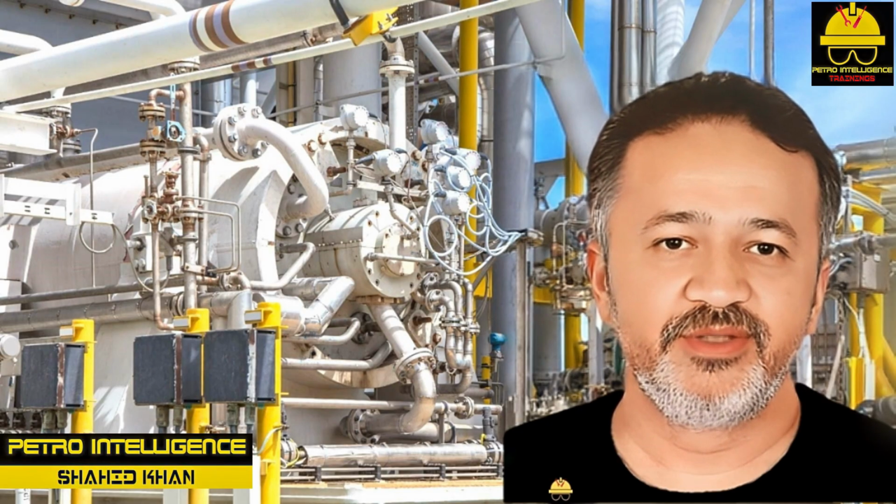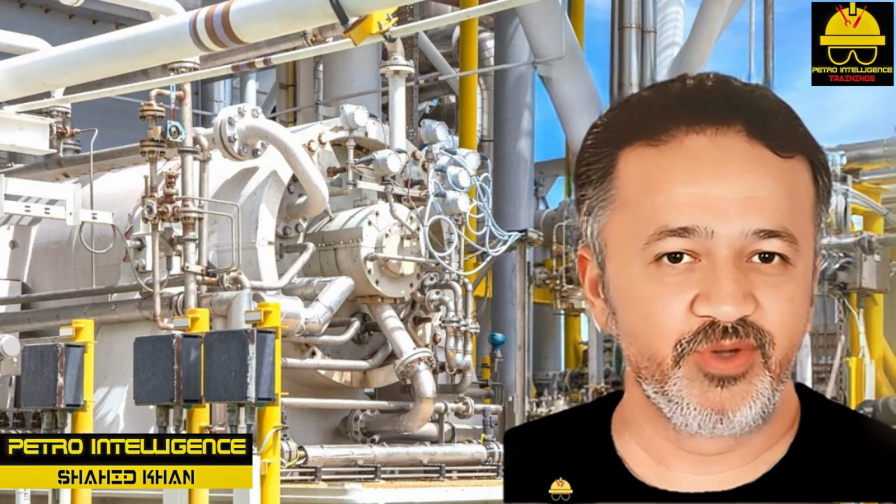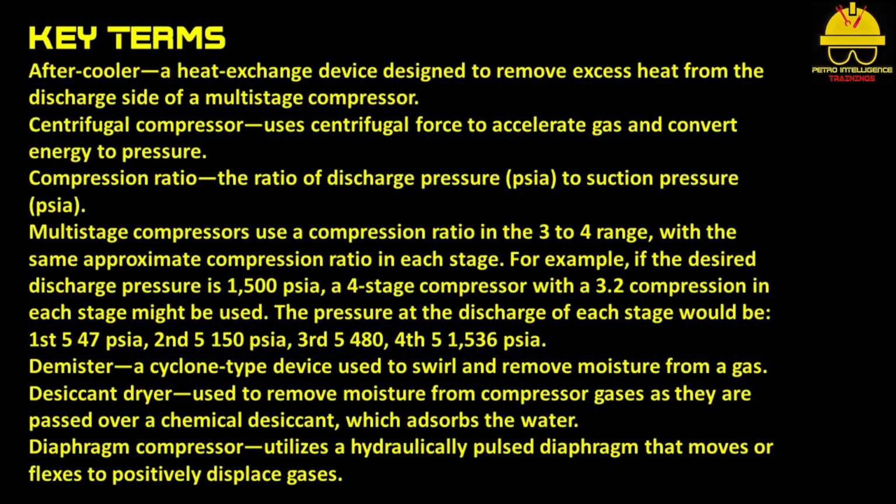Before starting the course, let's have a look at key terms of compressors. Aftercooler is a heat exchange device designed to remove excess heat from the discharge side of a multistage compressor. Centrifugal compressor uses centrifugal force to accelerate gas and convert energy to pressure. Compression ratio is the ratio of discharge pressure, PSIA, to suction pressure, PSIA.